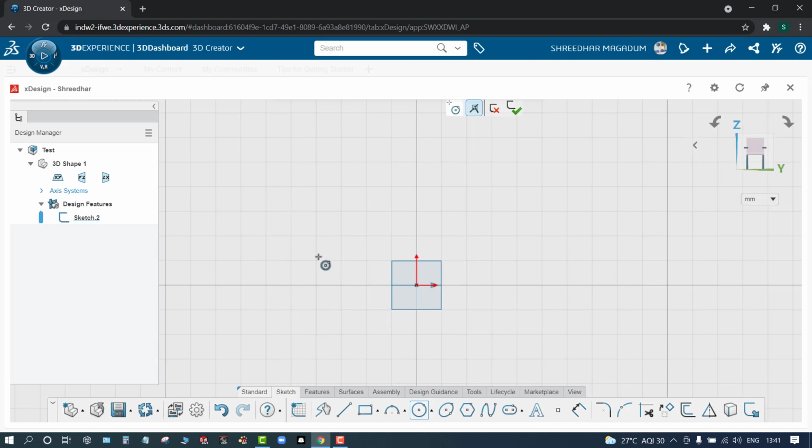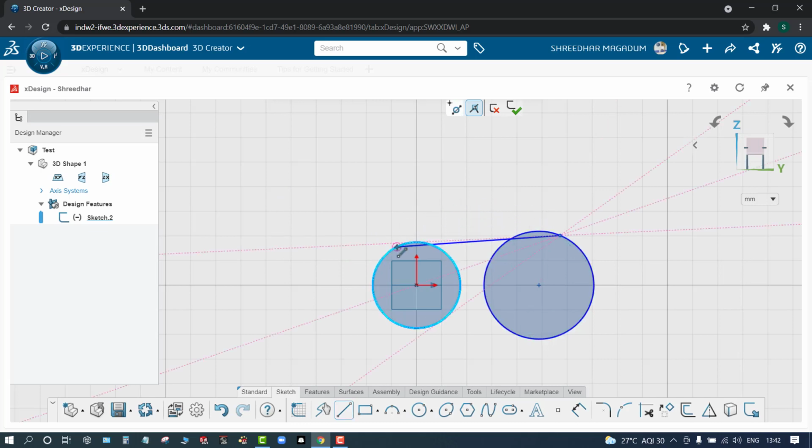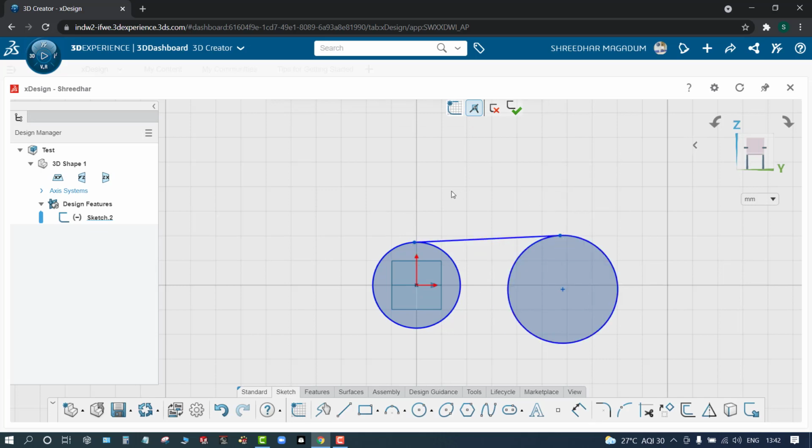To define the geometrical constraints, I'm gonna draw two circles, and I'll just align with origin, and then I'll add the tangent lines so that I can show you how things happen. You can use a quick drag and drop, and you can even define the tangency. If there is no quick access, you can simply, by just selecting the edges and the circle or lines, define the relations.